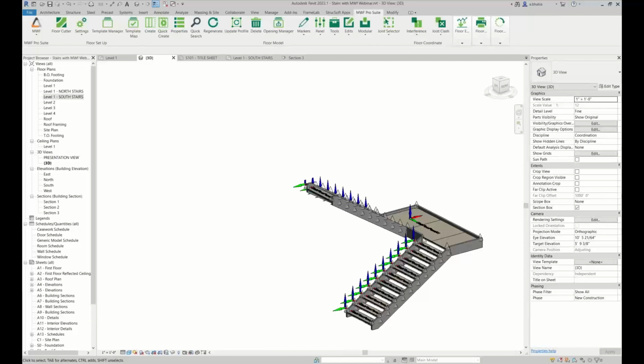No problem. So Colm said that I've used a wall panel to create stringers previously, but it's a bit messy. But yeah, I agree, it would be really messy. But if you really wanted to create something on the edges like this, I would create it as a floor panel that is the depth of the stringer. And then use your end joists or your rim joists, your end tracks, as your stringer material or your family for your stringer.